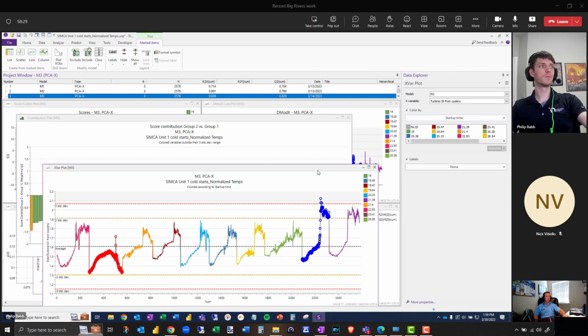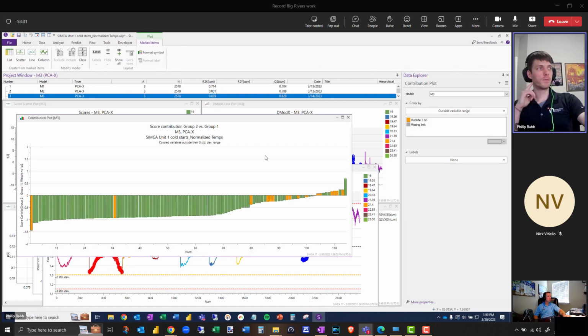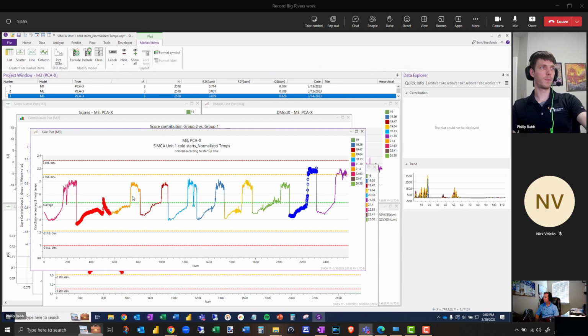And so that's a little bit of what we're doing with the software. We get it to a point where we start asking these types of questions, to try to pinpoint whether or not that makes sense from an operational standpoint. So here you can see all the bearing temperatures. These are all fairly large differences, and again, this bearing temperature is really low for June. So it probably took them a long time to get within an acceptable range to fire up the turbine.